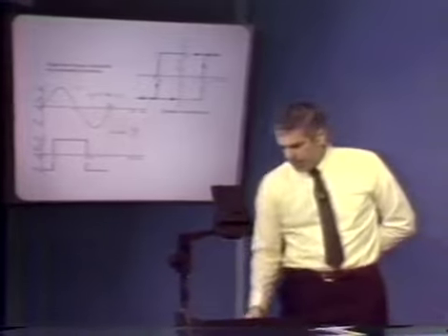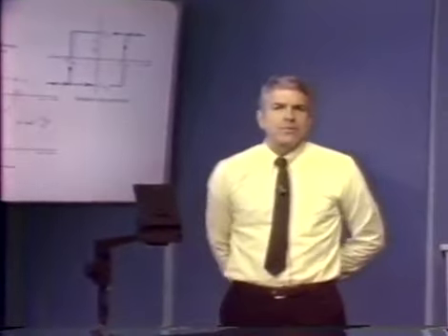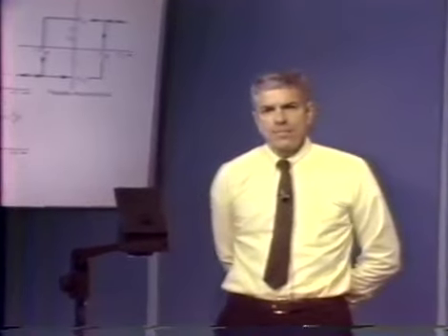Notice that this is an example of an element whose characteristics are frequency independent. We know nothing in this development about how to specify the frequency of operation of the Schmitt trigger. So its characteristics are frequency independent, yet it provides a phase shift. So here we have a slightly more complicated nonlinearity than we saw in the past. The phase shift sort of reflects the fact that the element has memory. In this case, the phase shift, though, in contrast to most of our linear elements that have energy storage where the phase shift is a function of operating frequency, in this case it's a function of driving amplitude.